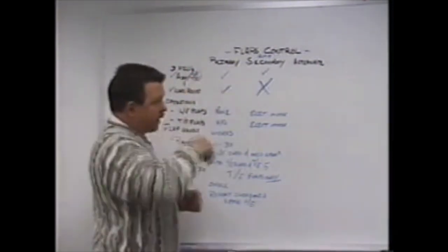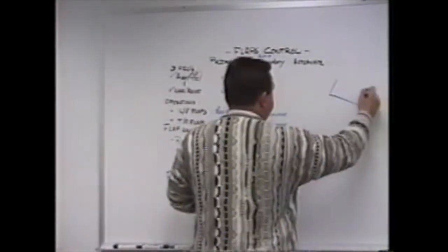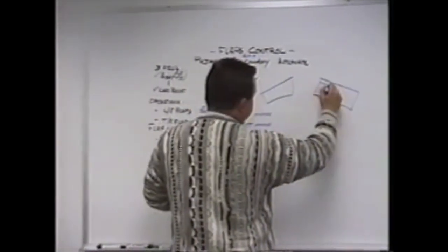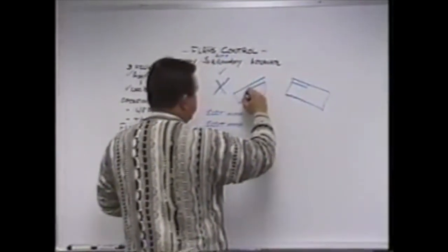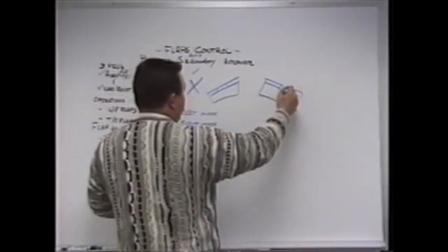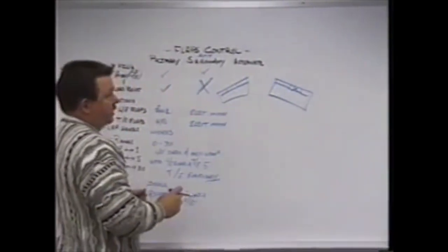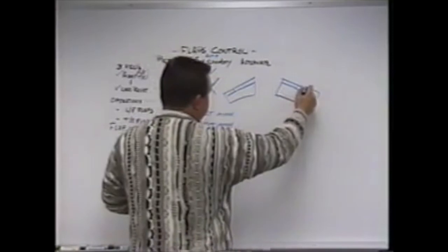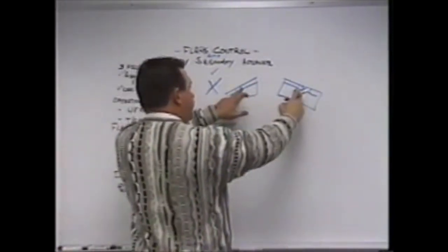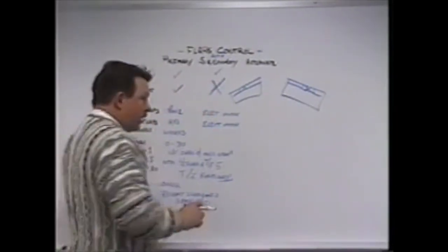Leading edge flaps. Let's just draw an example here. Let's say we have our left and right wing. These are not to scale, by the way. You've got the inboard segments, the midspan segment, and the outboard segments. If I was to encounter a problem with the right midspan leading edge flap, the symmetry protection would deploy the midspan electrically on the right wing and the left wing. So the symmetry protection will drive out both sides electrically. Everything else will continue pneumatically. Now, I need to get rid of that.